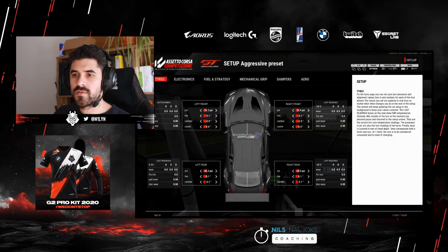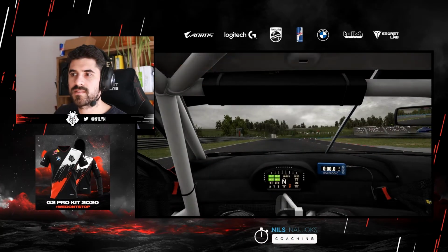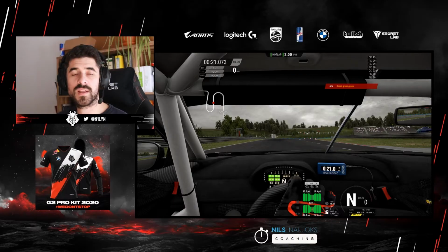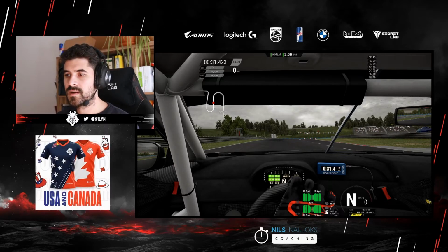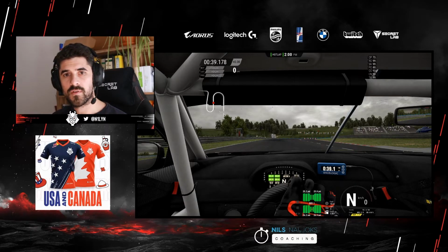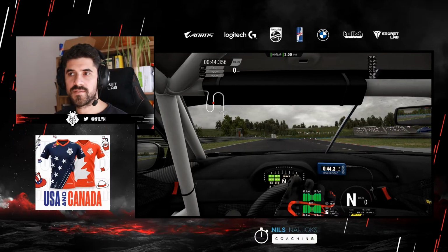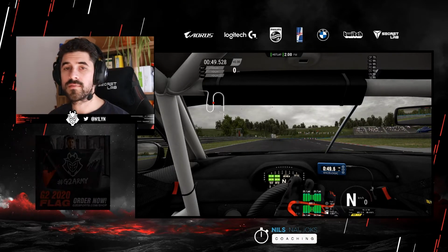Then as you take it to the track, let's just look at the front left here, all right? So 24.3 is a number you shall remember. Let's take it to the track, and now this number has changed to 25.3. This is because now the tires are preheated, so the pressure has already increased a bit with the air and the tire being hotter. Now as you start driving, you will see this temperature increases even more because of the rolling resistance of the tire, because of the cornering. So the surface heats up, and the whole rubber, the different parts of the tire will heat up, and the pressure in the tire will increase even more.